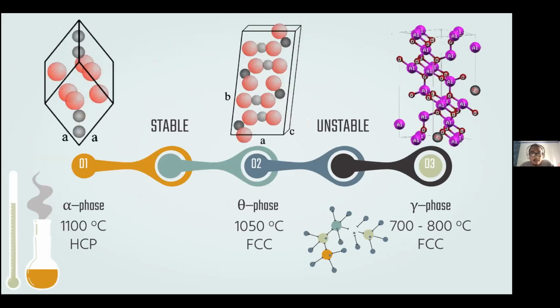Aluminum oxide is a polycrystalline ceramic material that is presented in different phases according to its alumina purity and both physical and mechanical properties. The crystal lattice exists in three types of phase: the gamma phase, the theta phase, and the alpha phase. The gamma and theta phases are unstable forms of aluminum oxide and will shift into other phases at certain temperatures.